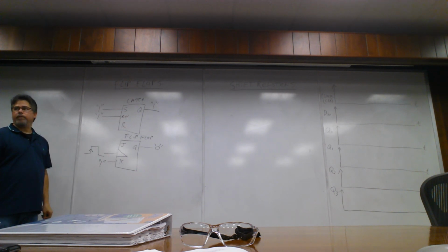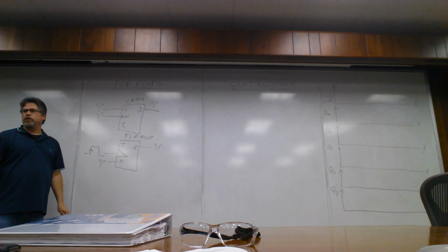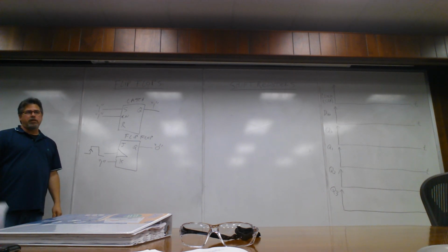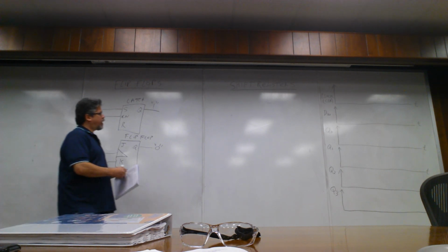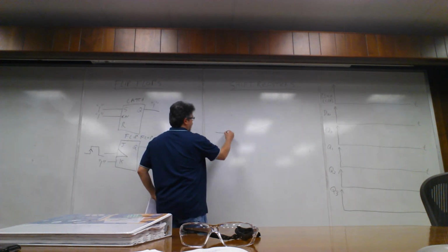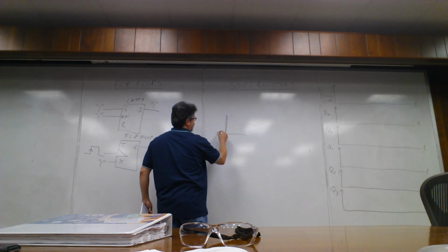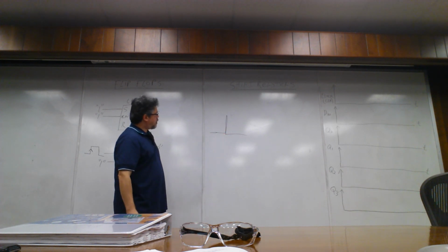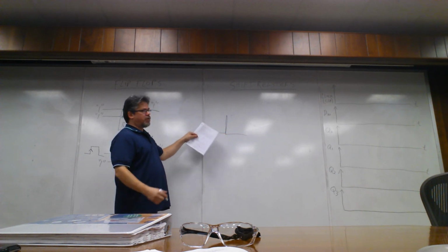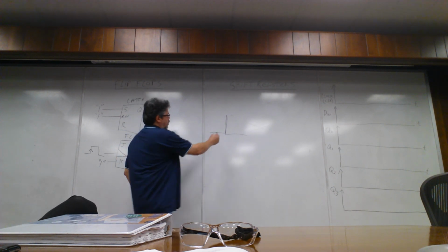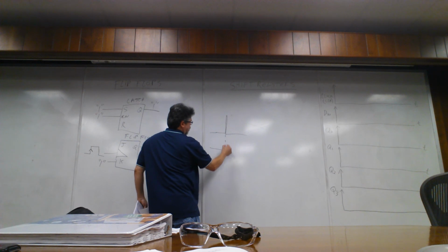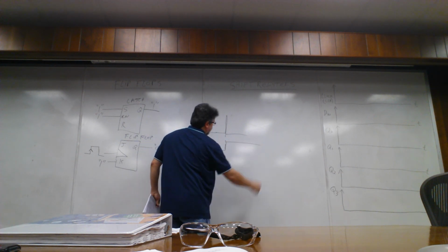This is what you were using as an example for contact bounce the other day, right? Exactly, and that's for the latch. That was the other purpose, contact bounce, because the latch acts like a one-shot circuit. If you had a very quick transition and we want to detect some kind of glitch out there, the latch would detect that glitch and stay high.